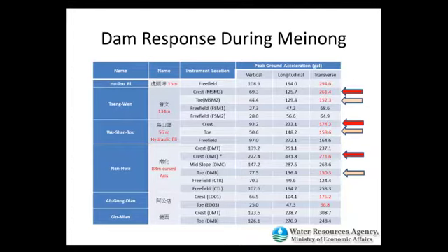There were a lot of dams that were shaken by this earthquake, including the tallest dam in Taiwan, Jiun-Wei Dam, which is 134 meters. The crest of the dam had been shaken to 261 gals, or 0.25 G. And the other tall one is the 88-meter Nanhua Dam. This is a curved axis embankment dam. The top of the dam recorded a peak ground acceleration of about 0.3 G.